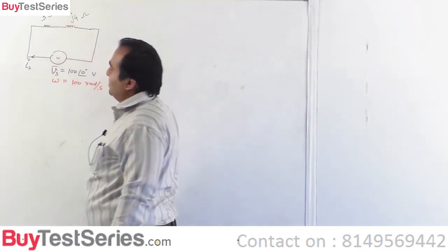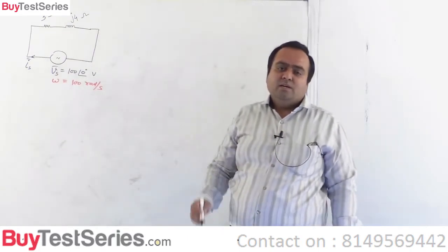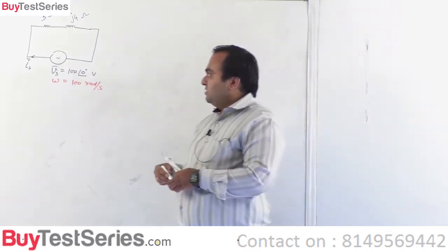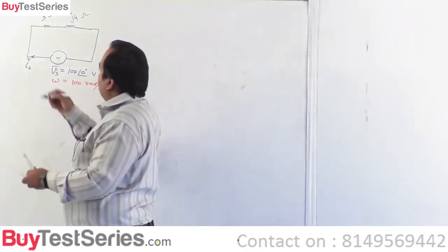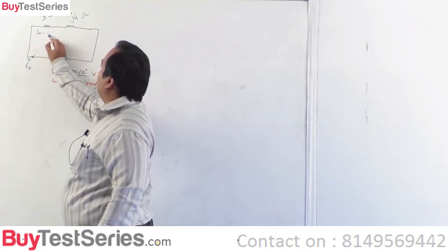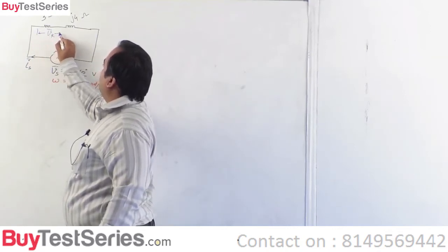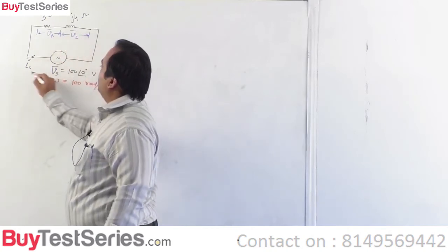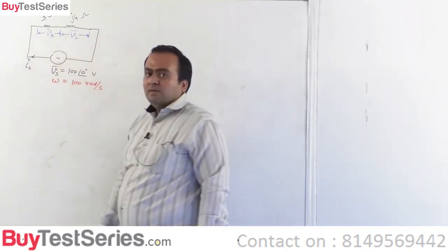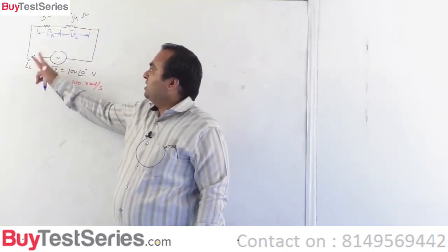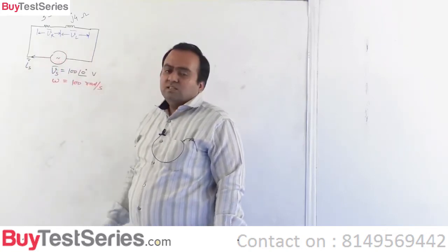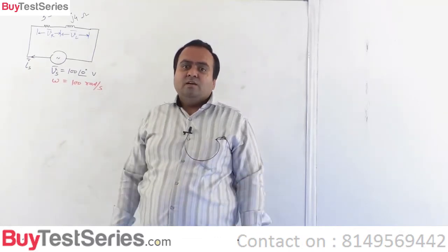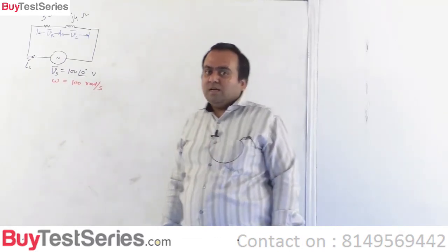J4 ohms, right? So 0.04 Henry can be replaced by J4 ohms in the circuit. Now what are the phasors that we shall indicate? This is VR, voltage across the resistance, voltage across the inductance, the source current, the source voltage. Alright, so source voltage, source current, resistance voltage, resistance current, these four are the phasors that we shall calculate, and with the help of these phasors we shall calculate very many things for this numerical.